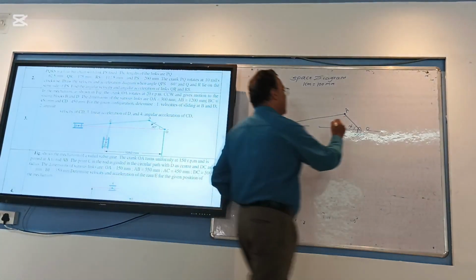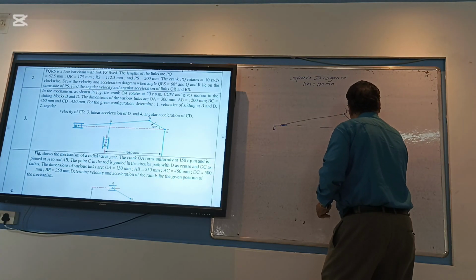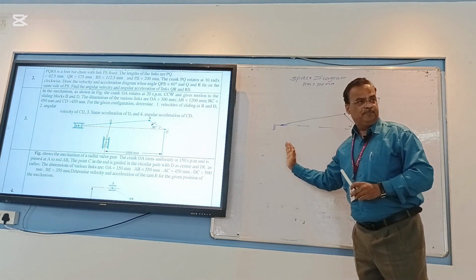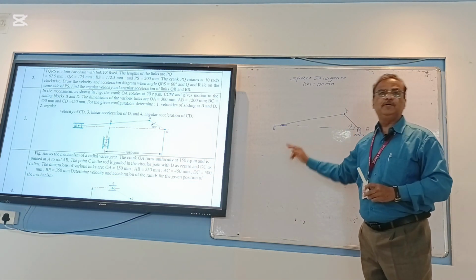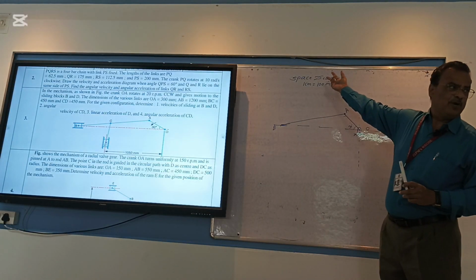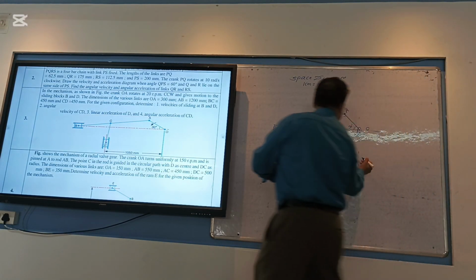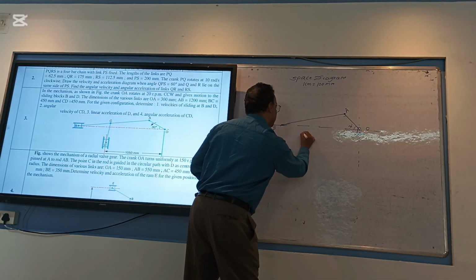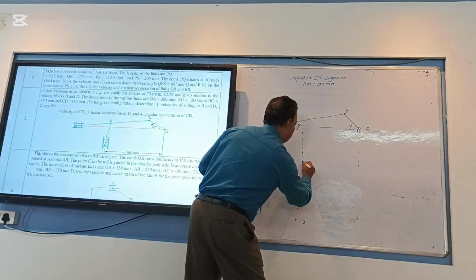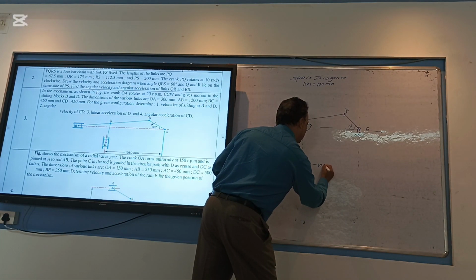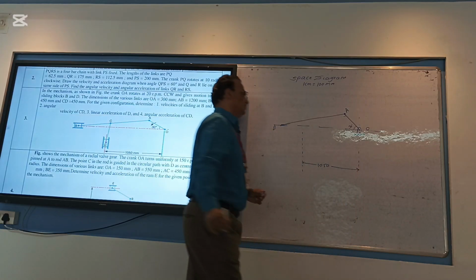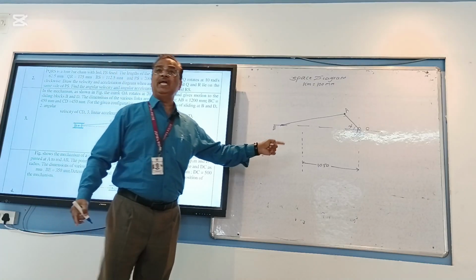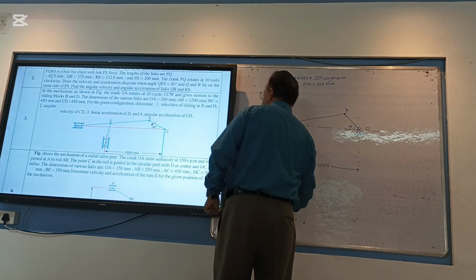So from the vertical line of this O, you have to measure the horizontal distance of 1050, as per your scale it is 10.5. Measure the 10.5 horizontally. Let's consider that 10.5 is coming here. This is the 10.5 centimeter as per your scale, but originally it is 1050 mm. So I got this vertical line.